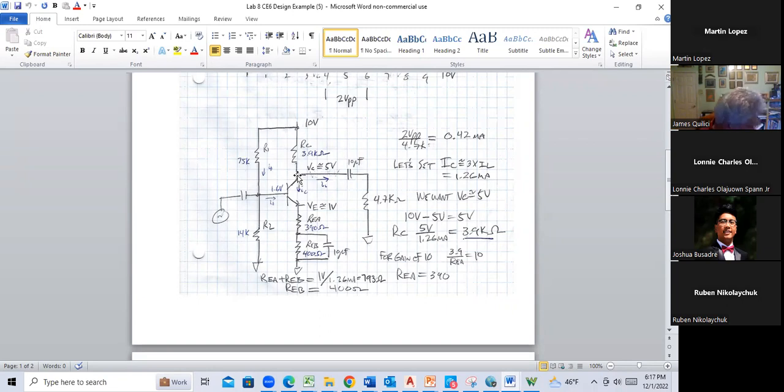If I put a larger resistor there, I'm going to put in a 2.2K and see if I can get this tuned up. Let me see if this will help bring the collector voltage up and also increase my gain. This is going to VCC. Not sure if I got that in there well.